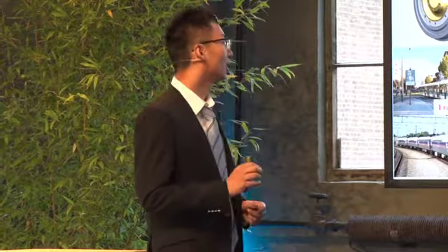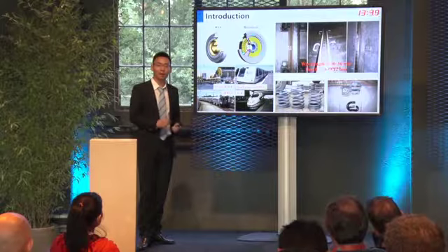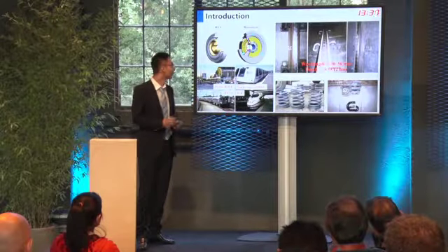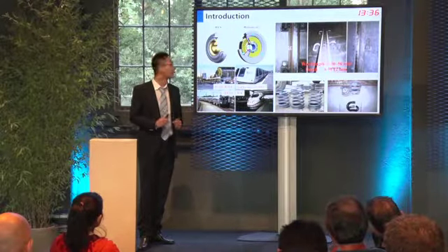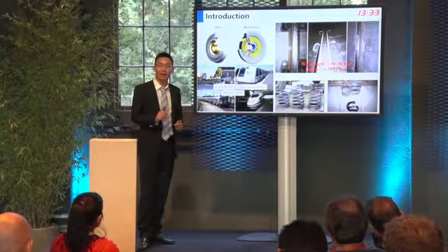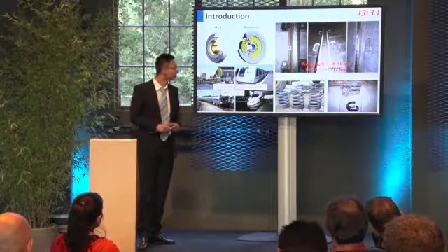Currently, many Chinese metro lines have suffered severe rail corrugation, causing abnormal vibration and noise problems in the vehicles and tracks, such as the fracture of the primary spring and the fastener clip. As a post-event countermeasure, resilient wheels have been proposed to reduce the vibration caused by rail corrugation.